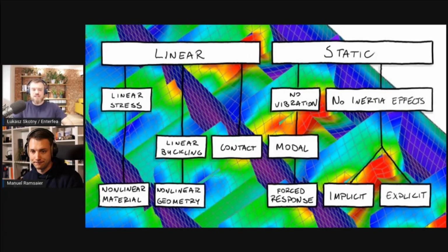It only depends on what you are trying to solve, because some problems will be prone to fatigue issues. Different things will be prone to buckling issues, but both of those can beautifully catch you off guard without any warning whatsoever. You just did your analysis, you think everything's fine, and suddenly you're in a place you didn't expect to find yourself in. Then it breaks. Buckling, completely different thing, right? So we have now linear and buckling.